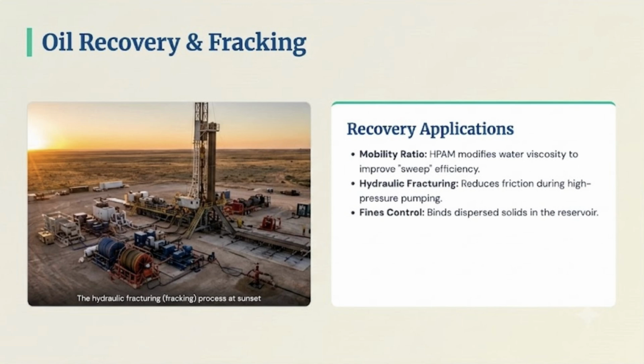For enhanced oil recovery, partially hydrolyzed polyacrylamide is added during water flooding to modify fluid viscosity and optimize the mobility ratio. This process dramatically improves the volumetric sweep efficiency across suitable oil reservoirs. Additionally, the polymer helps control fines migration by binding dispersed solids together.